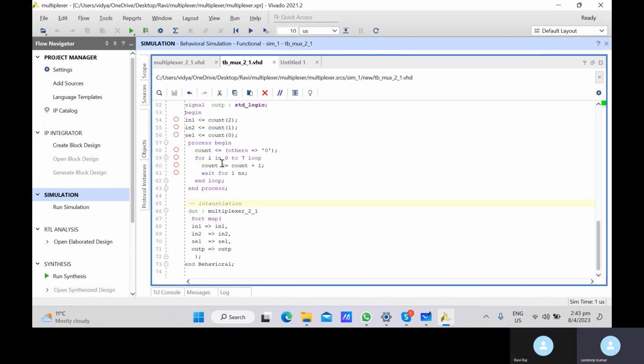Oh, you know what the problem is? Remember I said we have to have a delay right after each assignment, and only then does the value get assigned. You remember? But after this, we have not given any delay. So what happened? This value is not assigned as zero.